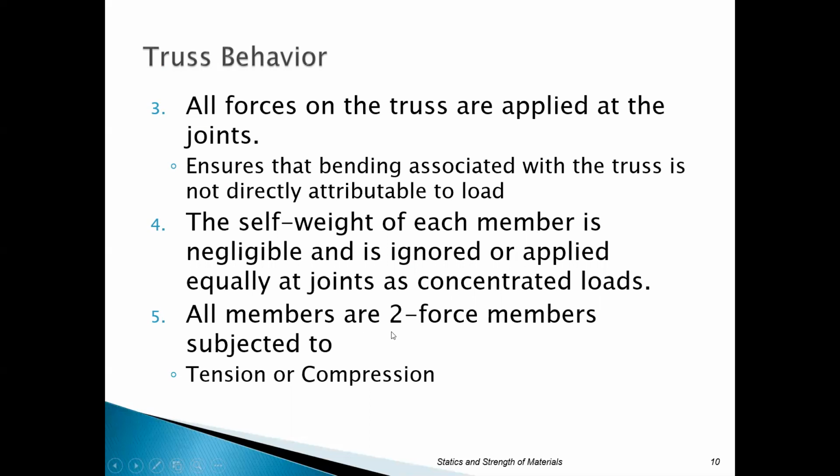And then all members are going to be considered two force members, and they're going to be either subjected to tension or compression. So this is going to be one of the harder aspects as you guys get into this. You do solve joint forces, but to turn that into a member force, you might come up with a number, okay, 12 kips, but then you also have to say, well, is that 12 kips tension or is that 12 kips compression? Because that's going to make a difference when you go to the next joint as you analyze it.